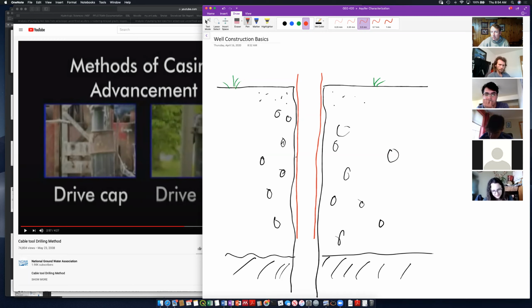All right, so there's two things. The hole will be irregular, and depending upon the drilling method, it can be very irregular. So these wireline holes, because you're just taking this bit and pounding away, they go everywhere. They're really rough, and they are not very smooth at all. They can be very wide in some places and very narrow in others. So it's not a perfect cylinder. We drive casing down, which, despite my imperfect lines, is a perfect cylinder.